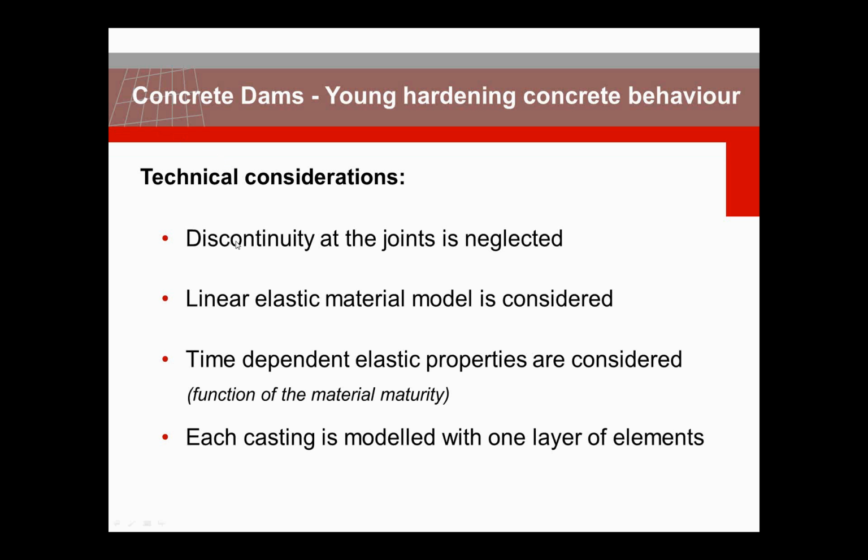We neglected the joints. We restricted ourselves to linear elastic material behavior, but looked into time-dependent behavior. So stiffness and tensile strength are functions of the maturity, and the thermal effects vary with time during this early age of the concrete.